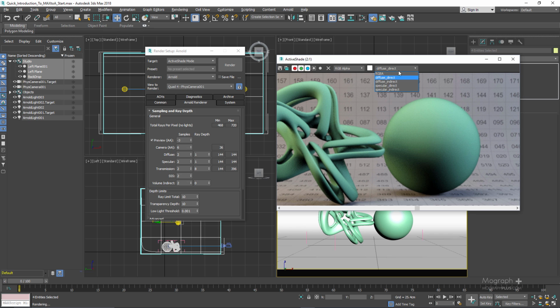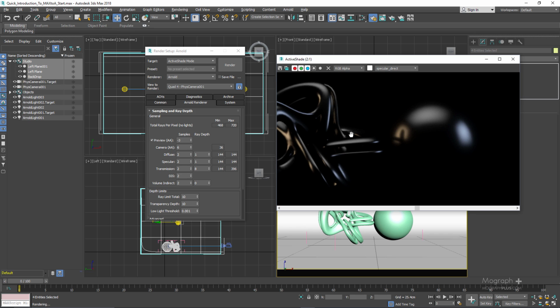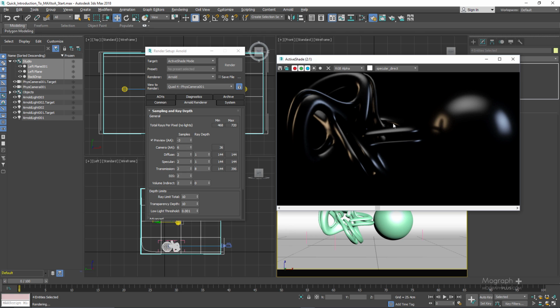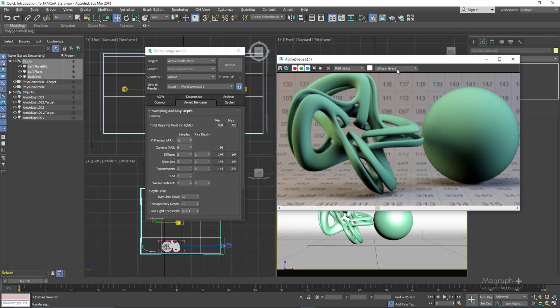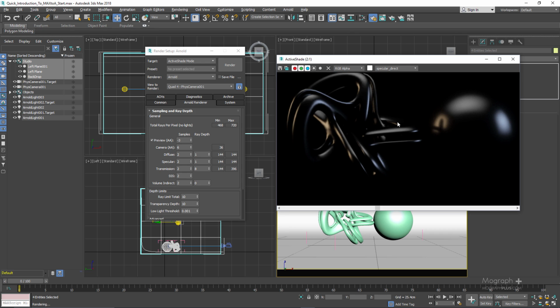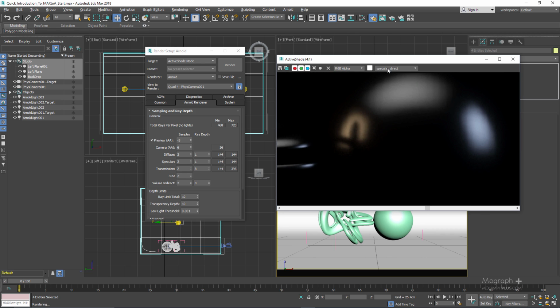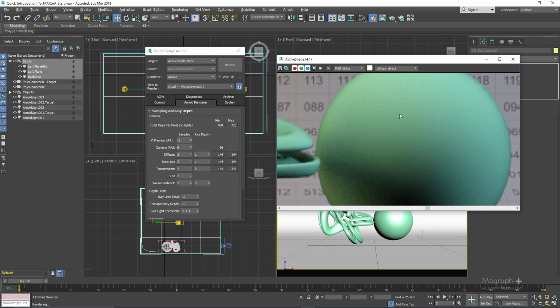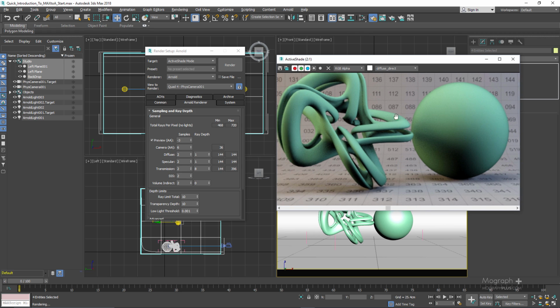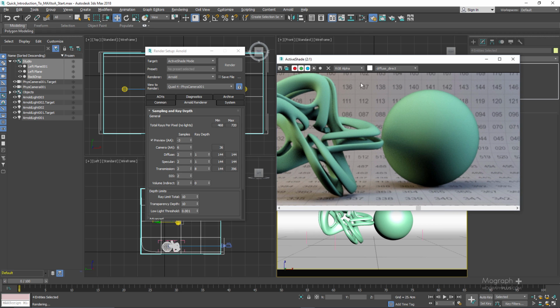In this AOV and also this specular direct, if we also saw some noise in this direct specular, the origin of that noise is coming from the light. In this case you can see the specular direct is quite clean, and the diffuse direct is not quite so clean. So we need to definitely increase our light samples to make sure these AOVs are cleaner, so the overall render